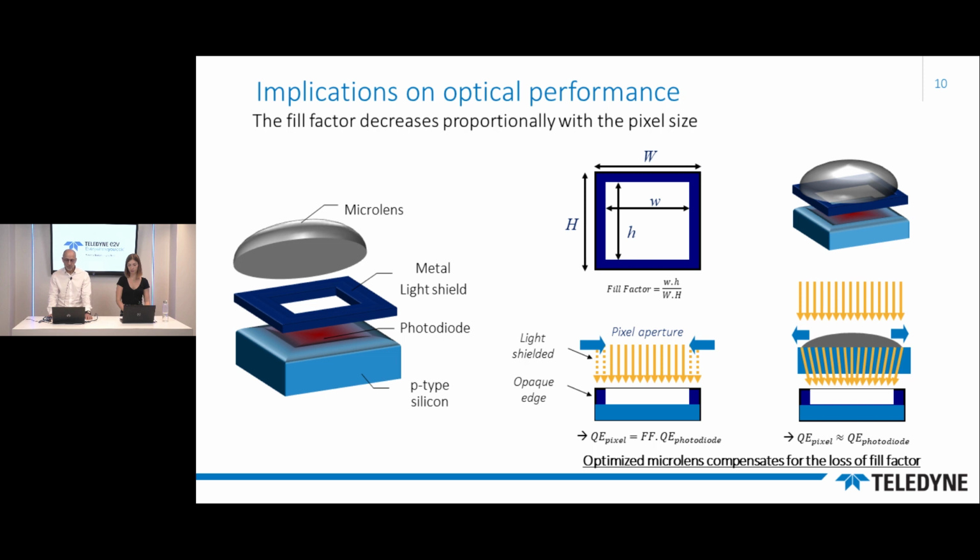So in the figure in the middle, the fill factor equals the lowercase xy divided by the uppercase XY, and that depicts the ratio of the sensitive area of the CMOS pixel, named fill factor. An alternative solution is to design a first-order microlens structure for each pixel, called a microlens, to avoid the constraints related to the operational condition.